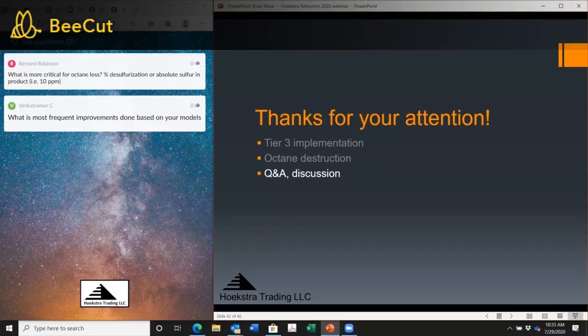Okay, it says, otherwise you may run it through the catalytic reformer such as a CCR to regain lost octane. Right. Unfortunately, we cannot modify catalyst selectivity to preferentially remove sulfur, but not saturate olefins or diolefins. Olefin saturation reaction is very easy. That is the problem. Well, I don't think the industry is at the ultimate in terms of selectivity that can be achieved in terms of getting higher levels of desulfurization with less octane loss.